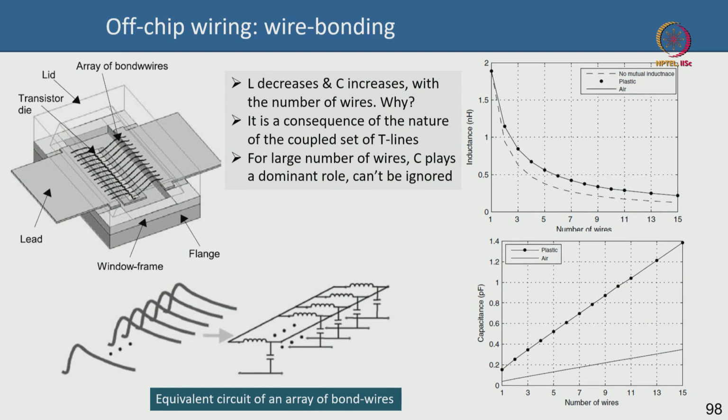Okay. Again, these are images of the bond wires. So you can see this is the inside of a package. Okay, you can see these bond wires connecting. There's probably a discrete LDMOS or a transistor or something there. It's a die which is attached to a metal flange of the package, and you have these wires that are connecting them. Okay, these are the bond wires.